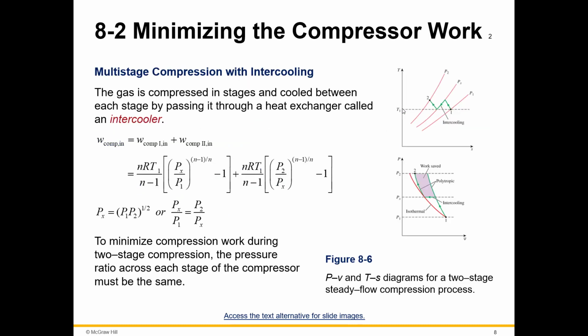The multi-stage compression with intercooling. So the gas is compressed in stages, and cooled in between each stage by passing through a heat exchanger called an intercooler. Remember we looked at that tube for the heat exchanger? Let's see. So you have this tube, right?